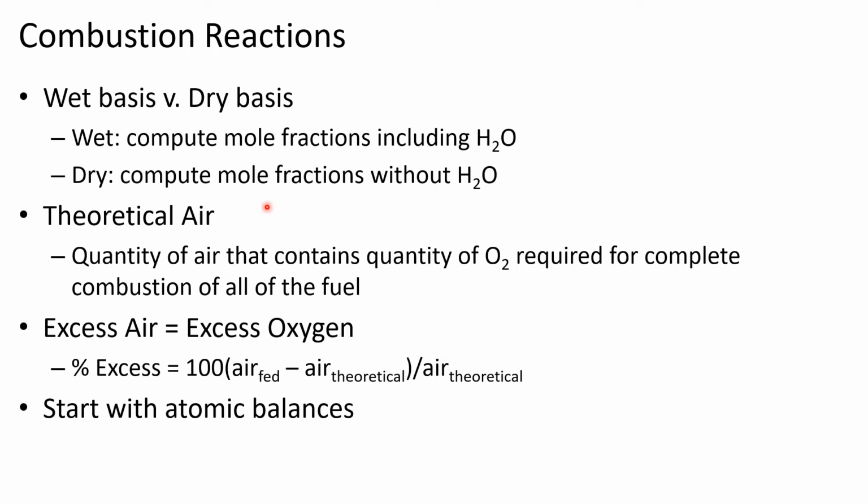Theoretical air really builds upon the description of theoretical amounts that we've talked about in previous reactions with problems involving reactors. The theoretical air is the quantity of air that contains the quantity of oxygen that's required for complete combustion of all of the fuel. So theoretical air includes not just the theoretical quantity of oxygen required for complete combustion or complete reaction, but it also includes nitrogen that would come along with it.